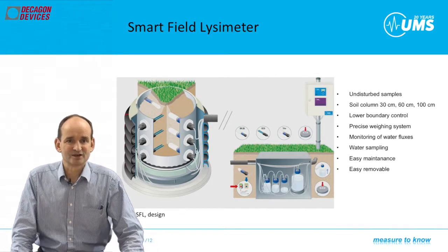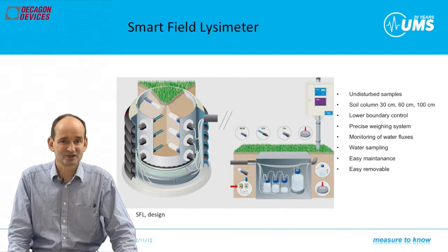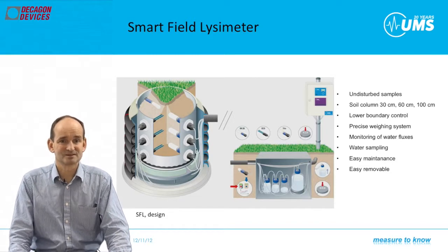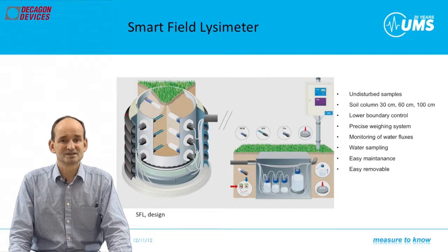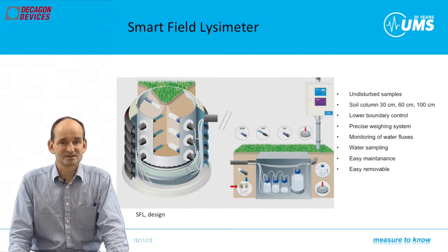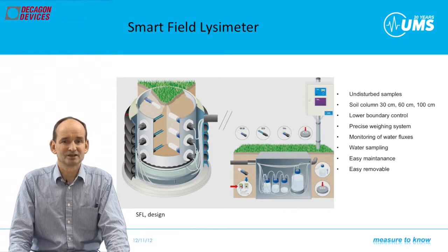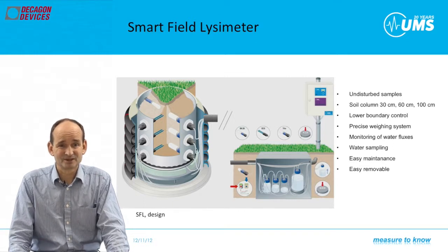The logger cabinet is now made of stainless steel, IP69 protection, and it's smart because of its smart dimensions of 40 by 40 centimeters. This is mounted on a stainless steel mast. The logger cabinet contains the DT80M data logger, the power management, pump controllers for each lysimeter, lightning protection, and a 26 ampere hour 12-volt battery. It is assembled with a small panel inside the door to facilitate the maintenance visits. Mast and lightning protection is prepared as well.